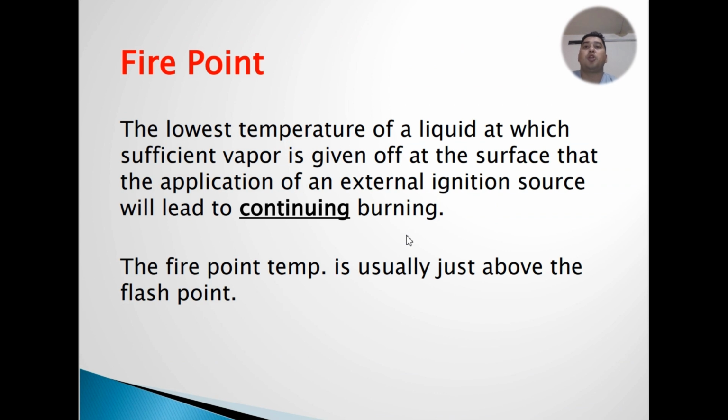Now the fire point: the lowest temperature of a liquid at which sufficient vapor is given off at the surface that the application of an external ignition source will lead to continuous burning. The fire point temperature is usually just above the flash point. So solvents have a flash point, and after that there is a fire point. When any solvent reaches the fire point, it will start to ignite continuously. So at the fire point, any solvent will start to burn continuously.